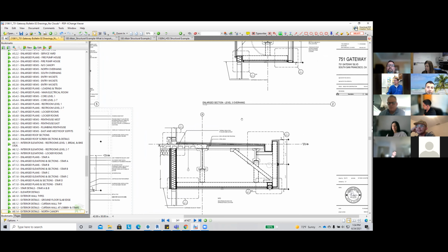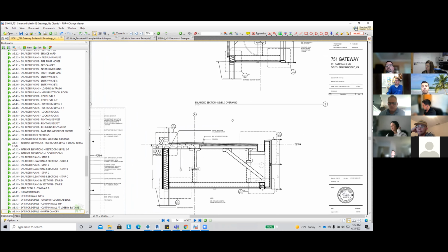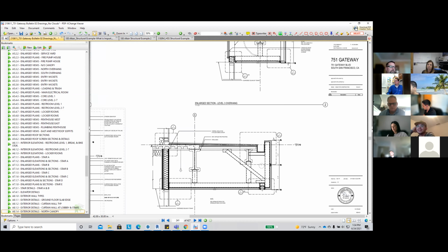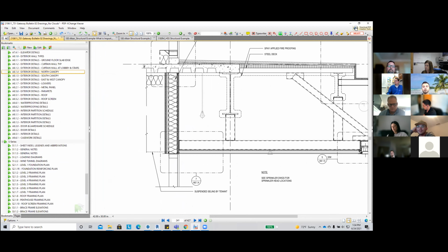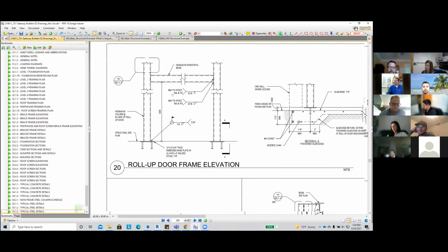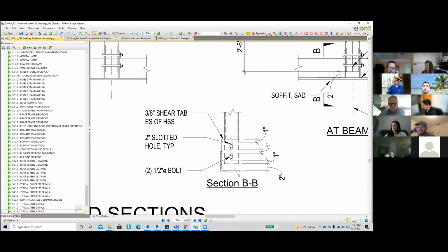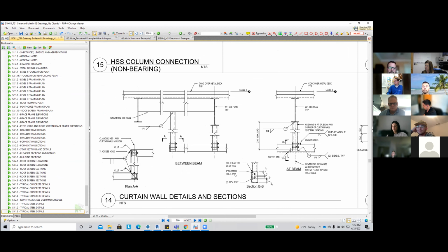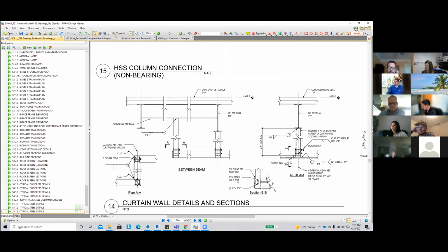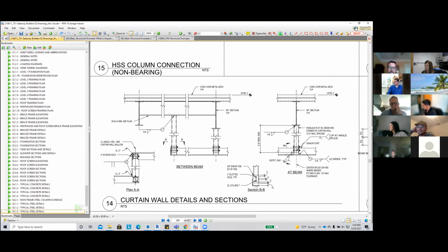And I think it goes back also to the whole thing of the architect not always being right. Sometimes even though they're working with the structural engineer of record and producing these drawings for them, the details don't match. For example, on this job, we're clearly showing stud framing at the head of the window, right? And that's what we drew, but when we went and verified, it's actually a steel angle running across at the head of the window. So it's a complete disconnect. If you don't do the due diligence, because probably the architect isn't going to do it for you, then you're going to go out to the field, and if this is out of tolerance, there's no way you're going to move it. It's going to be a nightmare.